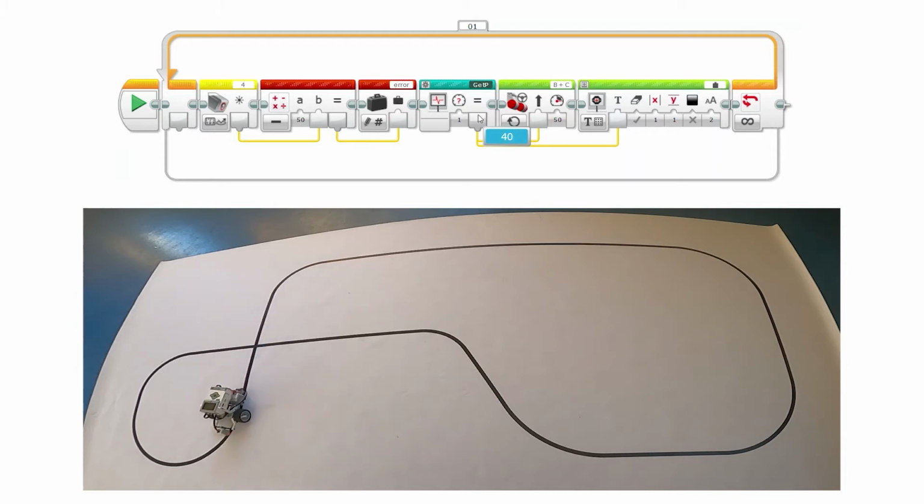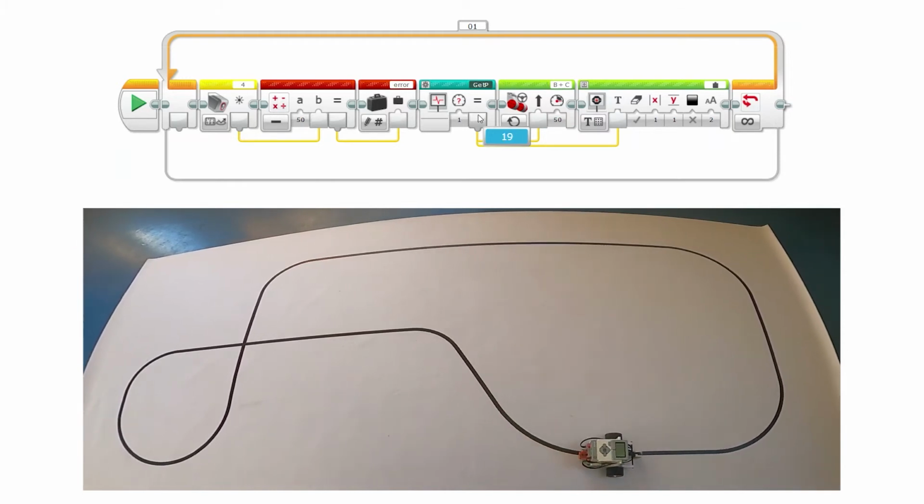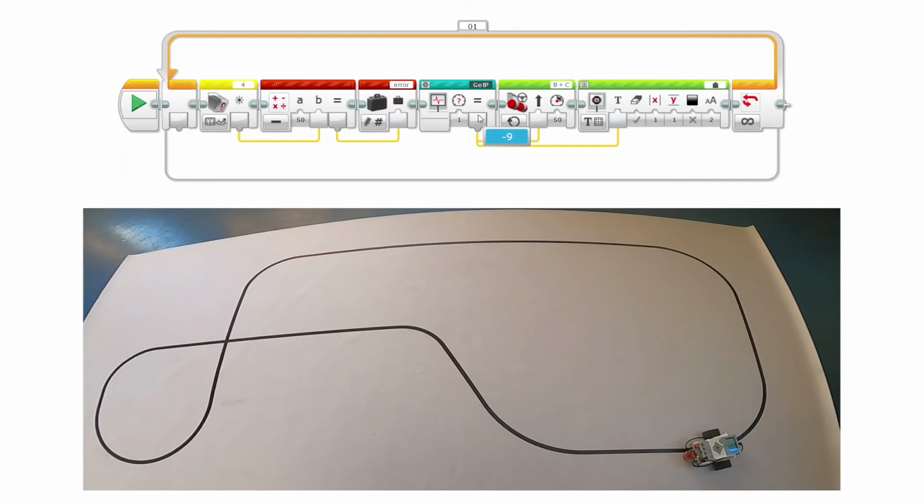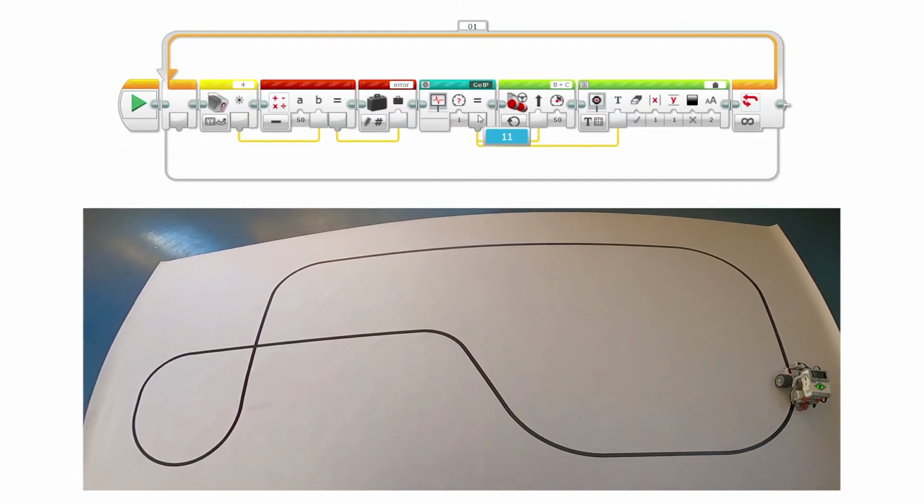Take into consideration that the light sensor readings may change if the light in the room changes. Testing the robot during the day with good light conditions might give good results, but testing the robot in the evening might fail. In our case, the motor speed is 50, which is half of the maximum value. Increasing the speed makes the robot wobble and it can slow down the forward movement of the robot, and sometimes the robot fails to follow the line.